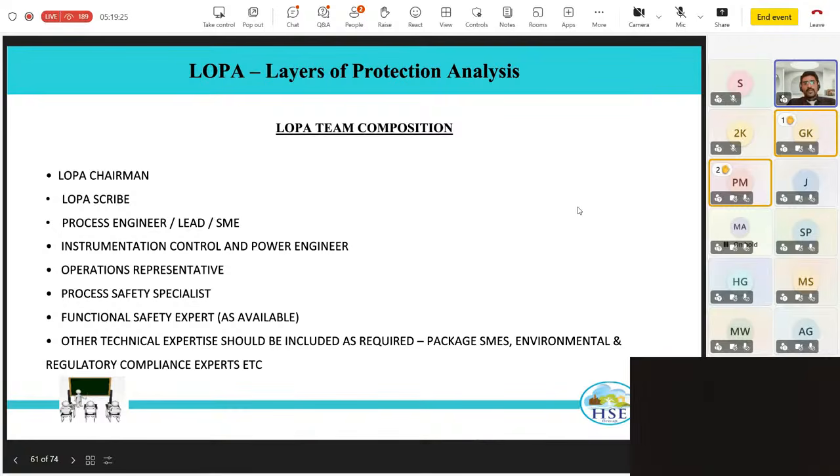The other one is when you have a control valve stuck open scenario. I'm just giving an example because it is interesting to know. When we design a CV failure scenario for a PSV, when you say control valve stuck open, you calculate the CV and the throughput through the control valve at full open CV, and that itself is many times higher than the throughput of the plant. Whatever flow rate you get through the control valve at full open CV is many times higher than the net throughput of the plant.